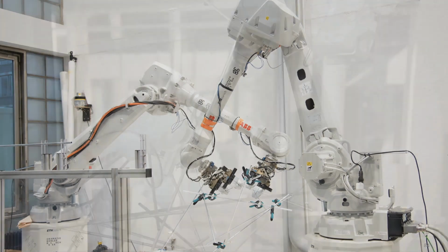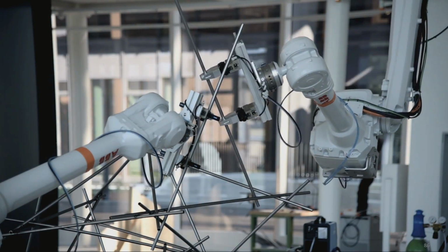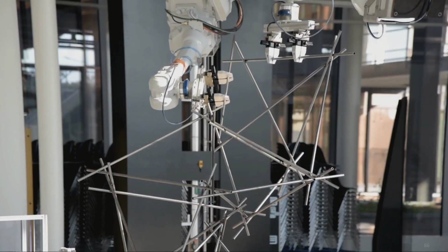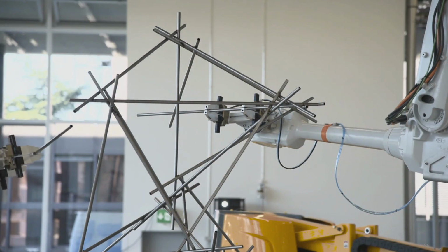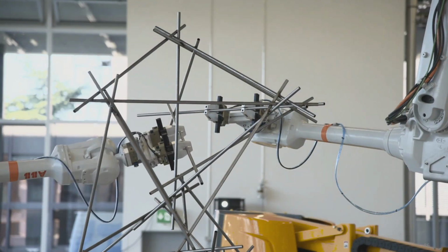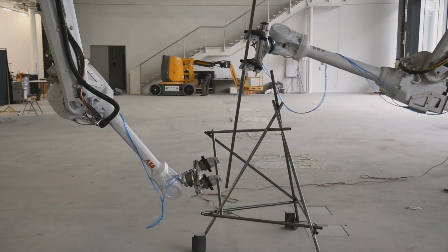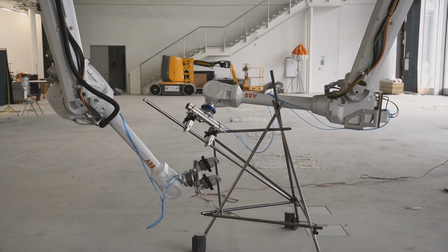So what this allowed me to do, this whole path planning process, is to generate these intricate paths to insert the elements in the existing structure without collisions, while ensuring the geometric integrity of the double tangent connection that I developed. So bars would literally have to be inserted in a specific movement to be able to connect to their neighboring bars in the required points.